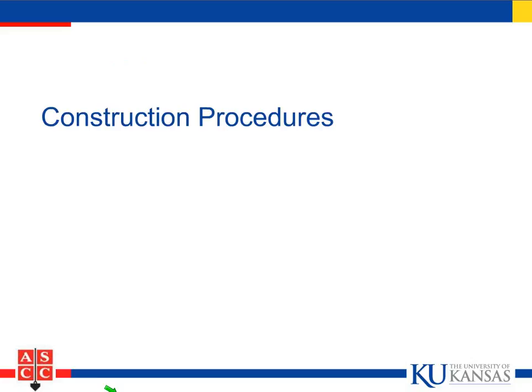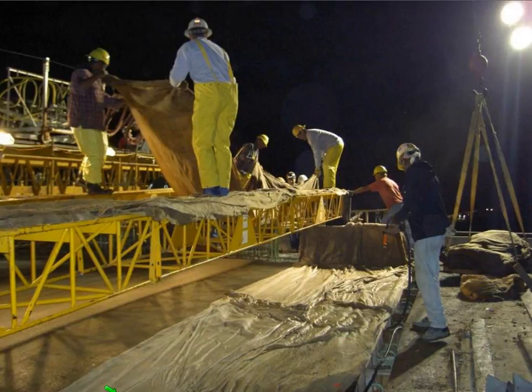Okay, let's talk about construction procedures. Key one here is curing. The trick is never let the concrete dry out until you're ready to let it dry out. Now this is a bridge deck, so we're not interested in getting a good hard trowel finish on this. We put 18 wheelers over it, and we're going to come back and groove this later. But what they're doing is right after finishing the concrete, and you see the finishing equipment is sitting right here, they're getting wet burlap right on it, pre-saturated wet burlap.